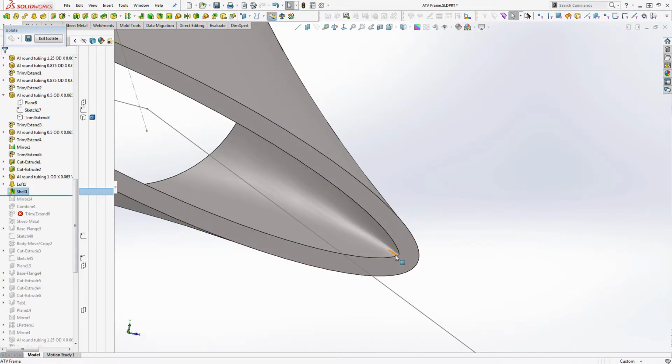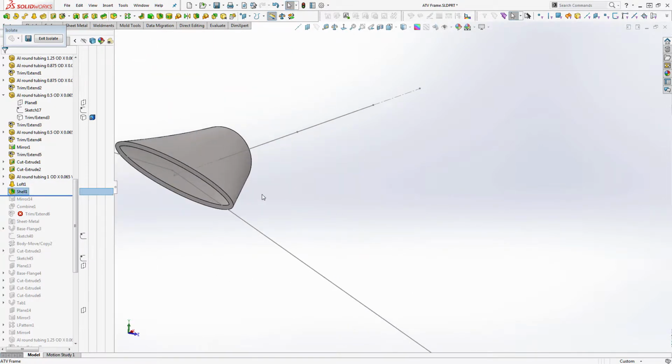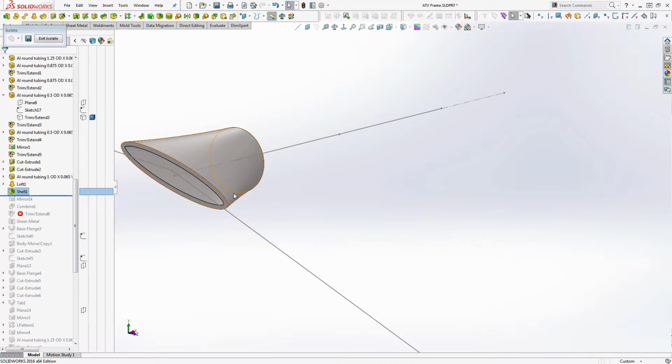Yeah, I'm starting to get pinching right here. It's so thin that it's starting to crush the tube. So what that would tell me is this tube may be too big, but regardless, I could have drawn an inner radius and probably did okay. But it is starting to get extreme, the flatness. I understand what's going on now.